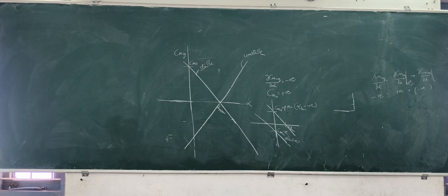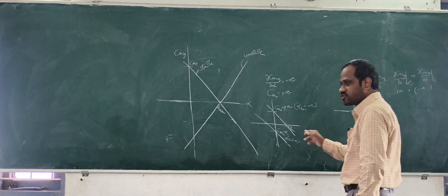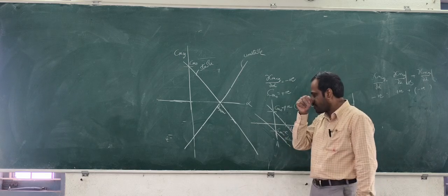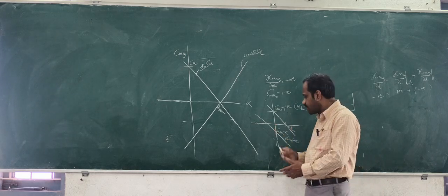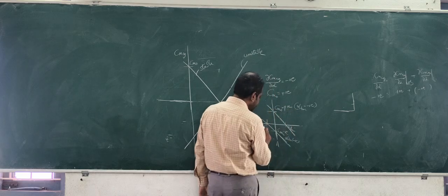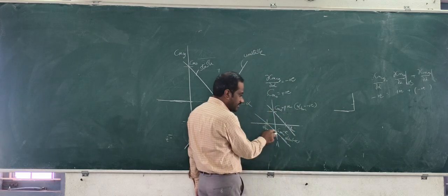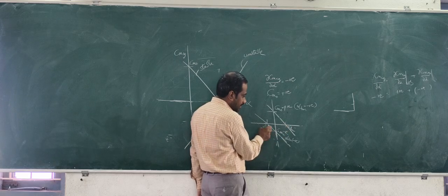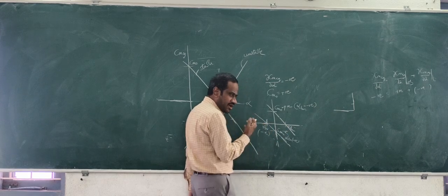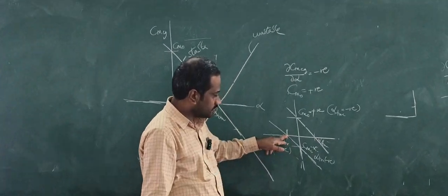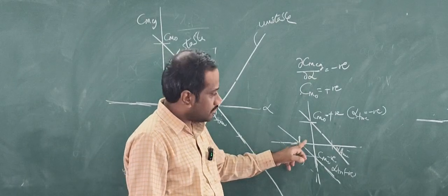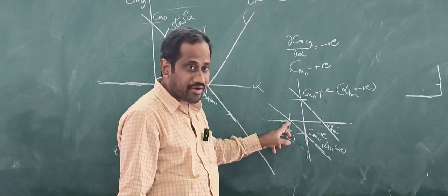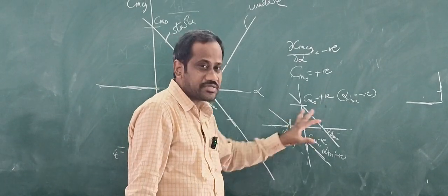Suppose the aircraft is disturbed, what type of equilibrium angle of attack does this aeroplane always look for? Once it is disturbed from equilibrium, it returns to equilibrium. What is the equilibrium angle of attack here? This is alpha trim. What is alpha trim for this graph? Negative. Look at what Cm naught is. This is the equilibrium angle of attack for this particular airplane, and this is the equilibrium angle of attack of this aeroplane. What is the difference between these two?